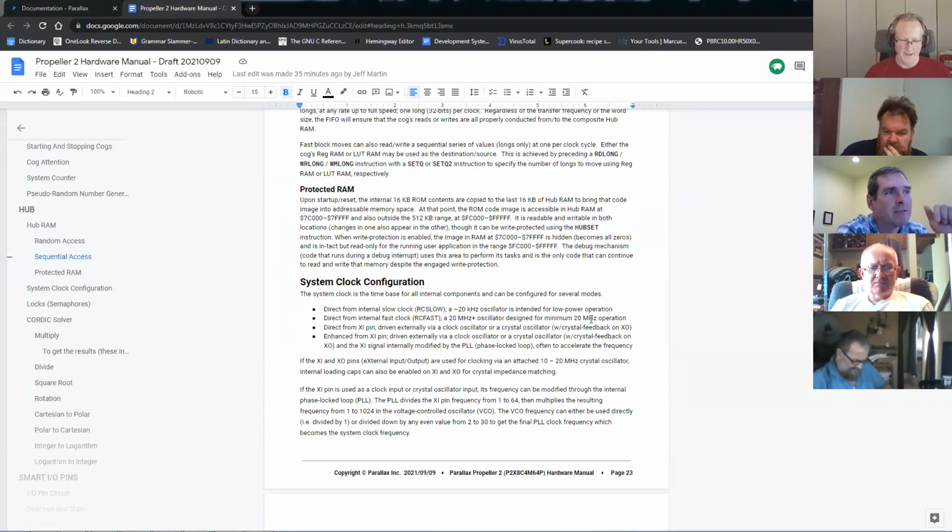Hey, Jeff. Yeah. I think the only other things you need to show in there are what happens when a stall occurs for whatever reason, and then what happens when a branch occurs. Because it has to assert the new instruction address, then it has to get that. So it costs 2 extra cycles because you have to dump 2 clocks worth of state in the pipeline that was for the instruction that you're not going to execute after all, but had been picked up.